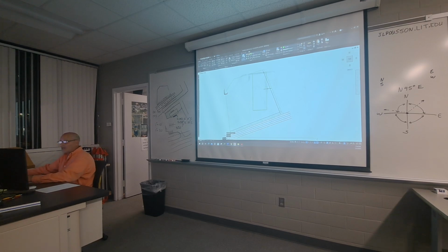So, if you say, I want my football field to be parallel with that property line, I'm going to first move it over there. The two ways that I do it, depending on what I feel like sometimes, or depending on which way I wanna do it. So here are 2 ways that I can get that position straight along that property line. Drawing it 90 degrees like I did, horizontal and vertical, is so much easier than doing all that offsetting and trimming to use your property line to draw it. You're wasting time. So I can go in either my rotate command, RO and space bar.